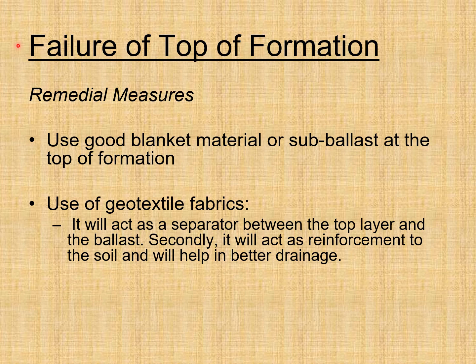Failure of top of formation, remedial measures. Use good blanket material or sub-ballast at the top of formation. Use of geotextile fabrics. It will act as separator between the top layer and the ballast. Secondly, it will act as reinforcement to the soil and will help in better drainage.